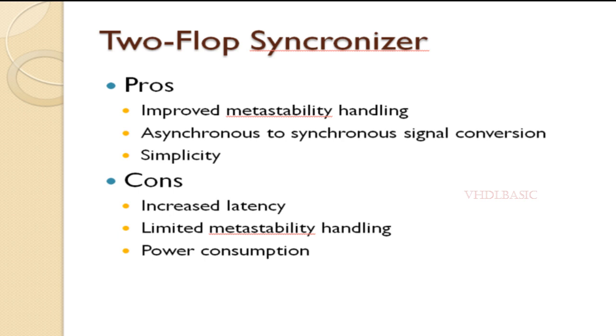Limited metastability handling. While the two flip-flop synchronizer reduces the chance of metastability, it does not completely eliminate the possibility. In rare cases, if both flip-flops capture a metastable state simultaneously, there is still a small probability of propagating the metastable value further downstream. Power consumption. Since the two flip-flop synchronizer requires an additional flip-flop, it consumes more power compared to the single flip-flop synchronizer. In power-sensitive designs, this increased power consumption may be a concern.